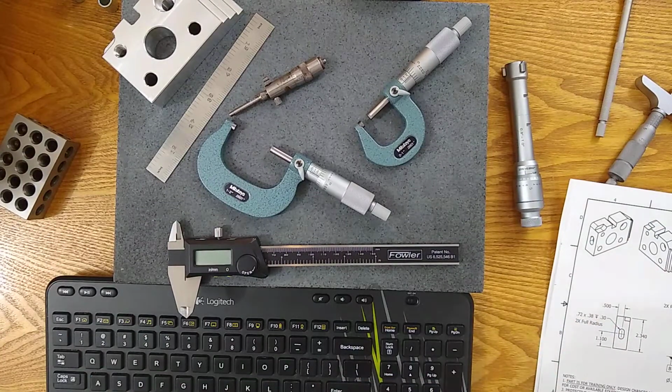So here's an example. Okay, large open tolerance outside diameter, and you have no large calipers, right? I mentioned it's large and it's open tolerance. So a caliper would be a great thing for an outside diameter if you have one, but there's none available. So do you want to use a large OD mic? Certainly possible. It's open tolerance, so you don't need to worry too much about making a mistake.